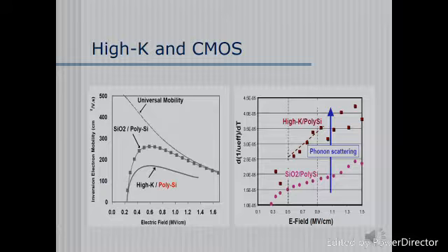After finding a proper metallic gate with an acceptable work function, we can introduce high Kappa metal gate transistors. Another way for high Kappa dielectrics to improve CMOS transistors is by using a gate all-around FET structure. A structure like this will be able to extend the Si channel to less than the 10 nanometer node, while continuing to allow the use of high Kappa gate dielectrics of modern times.